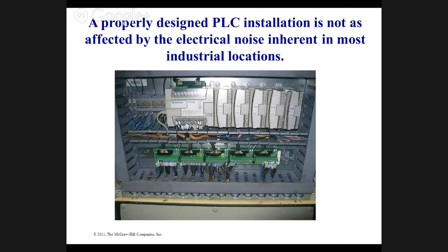So properly designed PLCs are not affected by electrical noise, like from AC drives or large motors or fluorescent lighting. What they're saying is that a home PC isn't shielded from electrical noise like a regular PLC is.